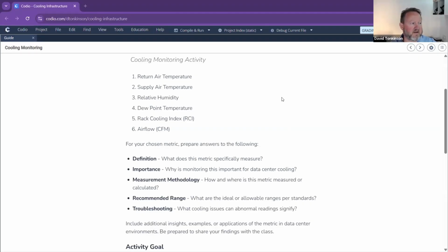Okay, I'll tell you what, let's do it the other way round. Oh, hold on, Daniel's gone. Daniel's pasted something in there that says the rack inlet temperature measures cold air supplied temperature entering the front of IT equipment. Simple and critical to ensure the rack stays within ASHRAE guidelines of 64 to 80 degrees Fahrenheit. Good cut and paste, I like that.